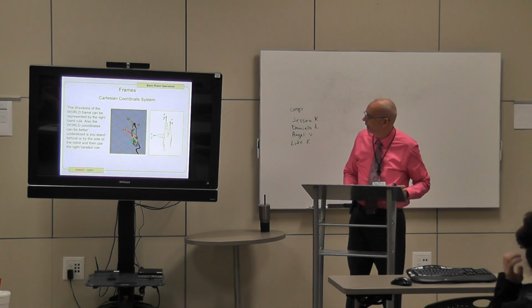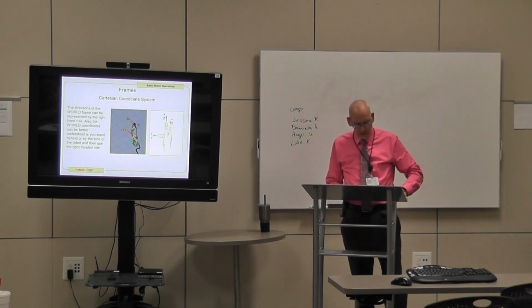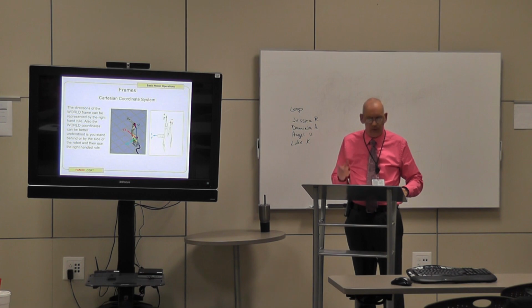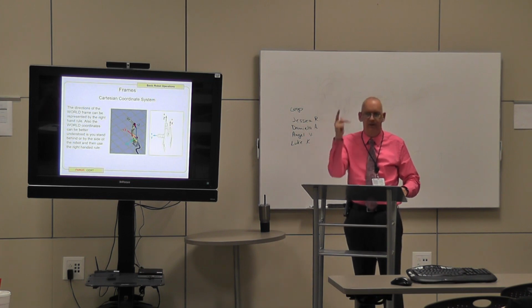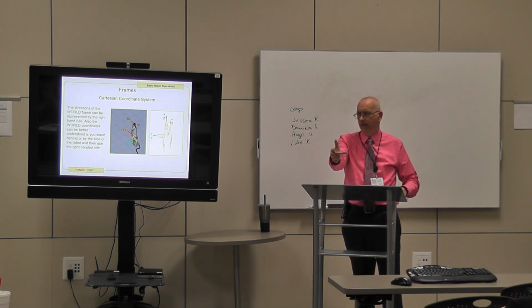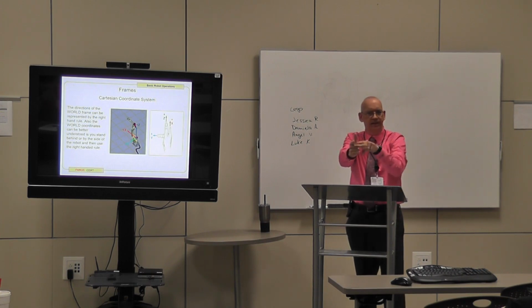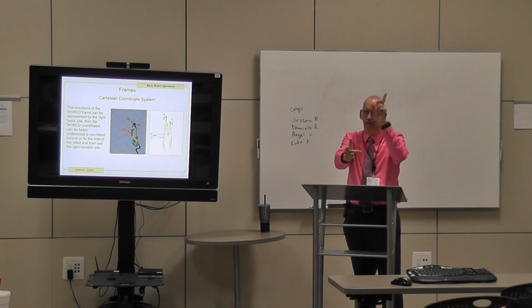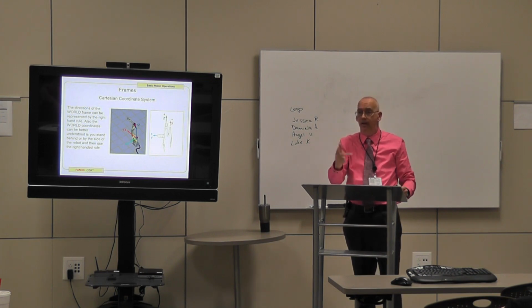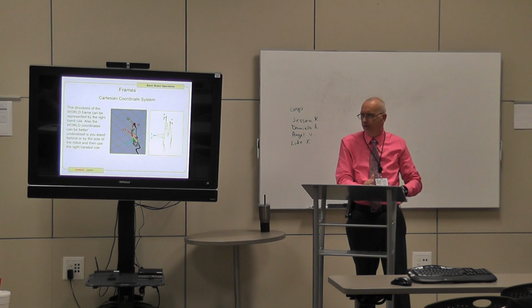Okay, let's move forward. The directions of the world frame can be represented by the right-hand rule of thumb. We did this last time, right? Everybody put up your right-hand rule of thumb. Okay, also, world coordinates can be better understood if you stand behind the robot or by the side of the robot using the right-hand rule. X being this way, moving forward and backward, Y moving side to side, and Z moving up and down. In a linear motion now, because we're in world mode using the world Cartesian coordinate system.